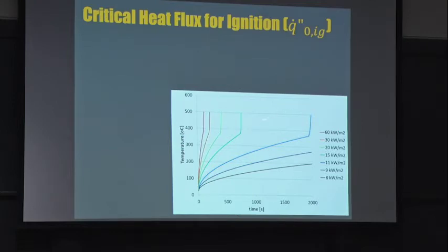And if you keep increasing the heat flux, the curve will keep growing beyond ignition if it didn't ignite, no? Because it won't reach thermal equilibrium until much, much later. Is that okay? So it will be truncated at the moment it ignites, okay? And if it will not ignite, it will keep increasing until it reaches thermal equilibrium at a much higher temperature. So this is my T ignition, and you're going to have the cases where it never gets there. In other words, you get to thermal equilibrium before you reach the ignition temperature.